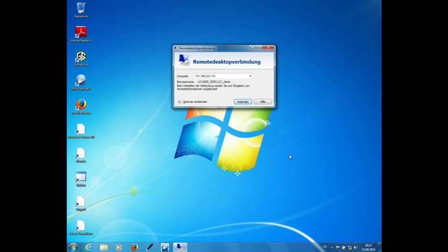Mini bake just means going to room temperature for a little while, like over the weekend or over a Christmas period. You can raise it to a moderate temperature by using the heater, but the easiest thing is just to switch the entire cryo pump off.